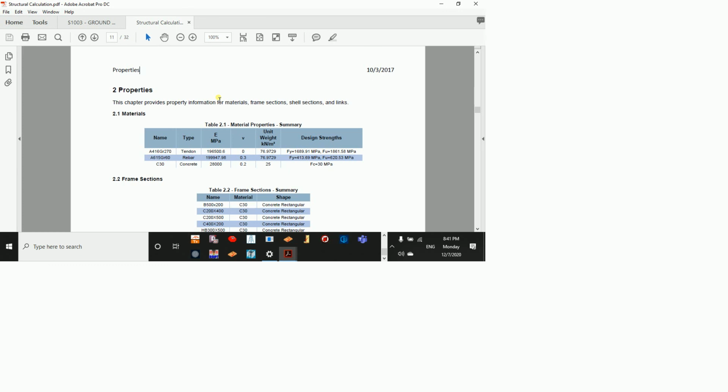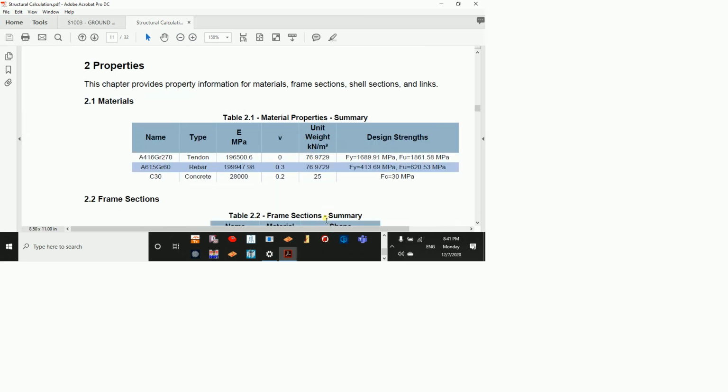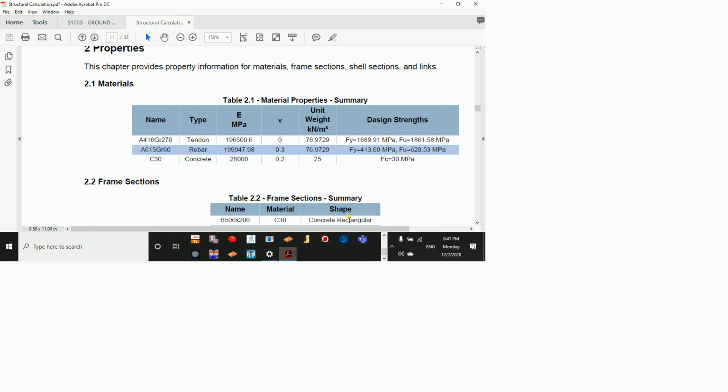That's a problem when it comes to ETABS. As I told you, here he has changed the grade of concrete, but he didn't change the other parameters. For example, for steel rebar, he's using 420. Why 420? Because that's what is available according to the American code.